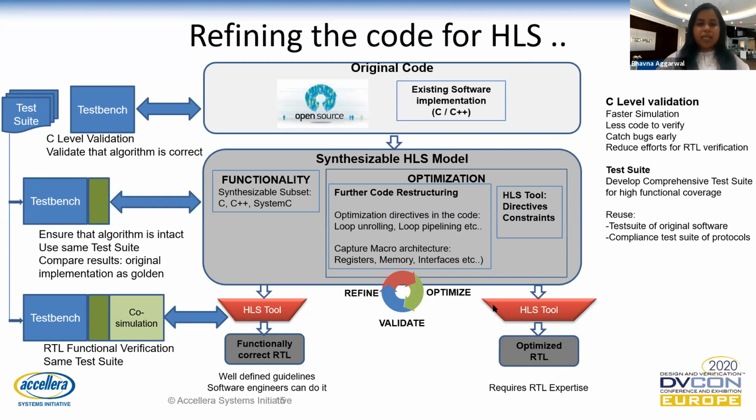It also requires restructuring of the synthesizable code to capture a bit of macro architecture in the form of registers, memory, interfaces, etc. This exercise requires strong understanding of the RTL and cannot be done by the software expert.